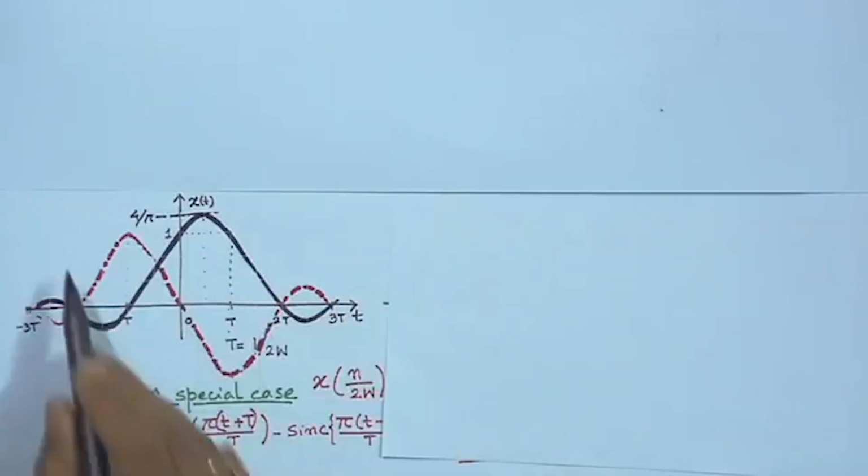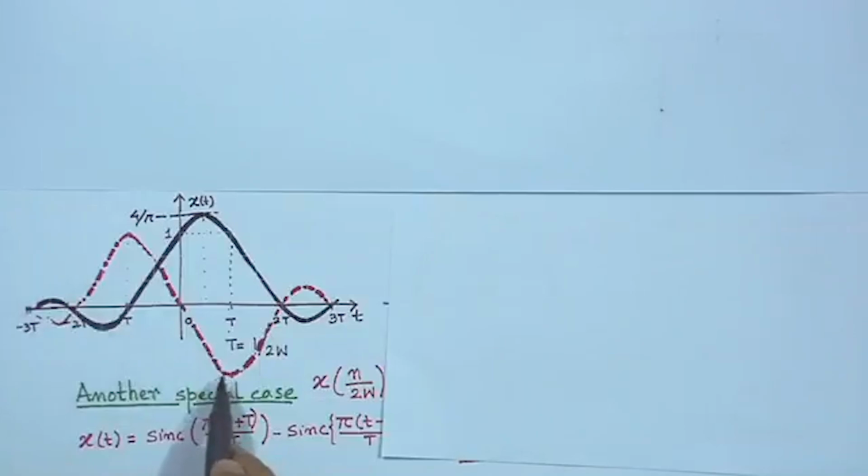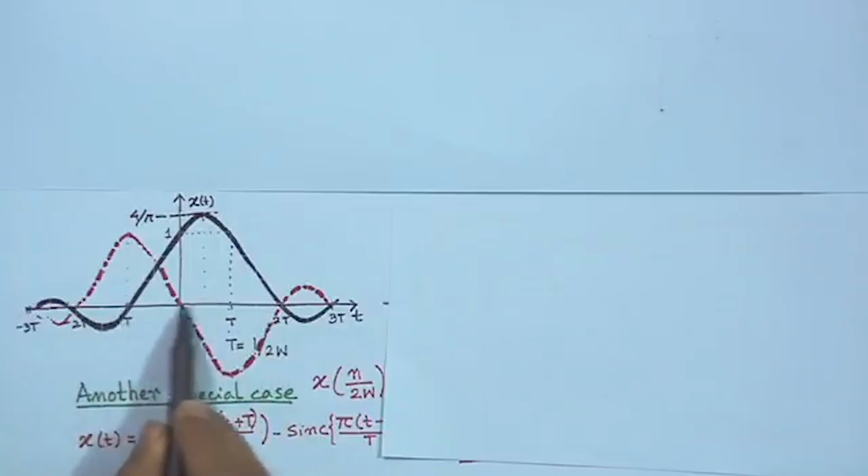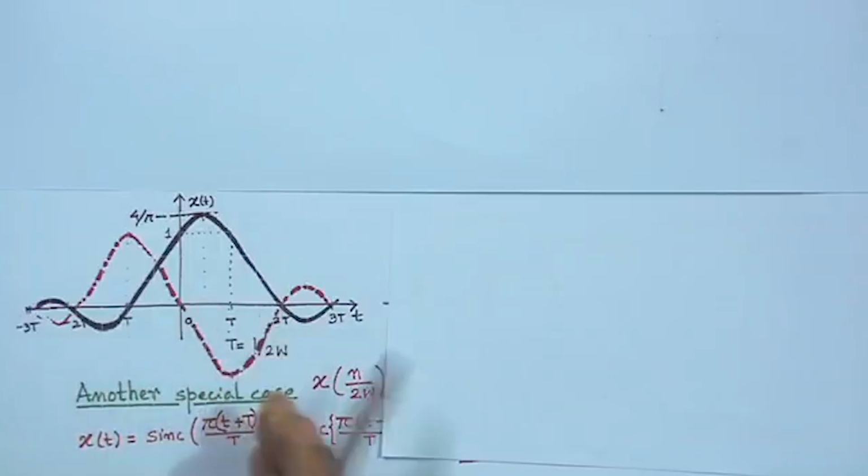So, it allows a certain amount of ISI, but since the span of the signal is more than the earlier situation, the bandwidth requirement will be smaller than the Nyquist bandwidth W_0, and if that is satisfied, the excess bandwidth up to Nyquist could be used for a smooth roll off, which we are going to see shortly.